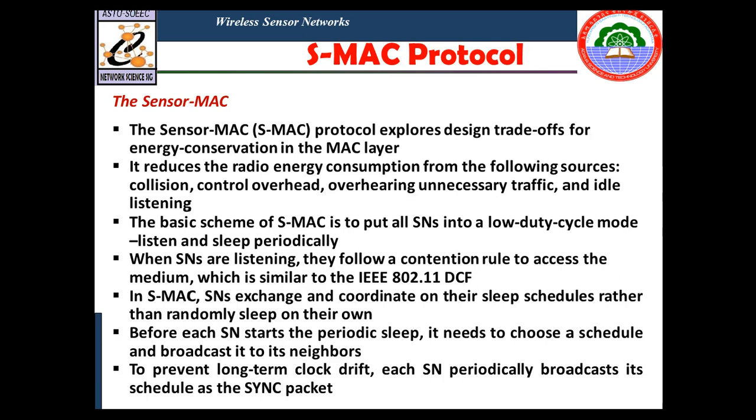Since only partial information about radio connectivity in a sensor network is used to assign time intervals to links, there is a potential for time collisions with slots assigned to adjacent links, whose existence is not known at the time of channel assignment. To reduce the likelihood of collisions, each link is required to operate at a different frequency. This frequency band is chosen at random from a large pool of possible choices when links are formed.